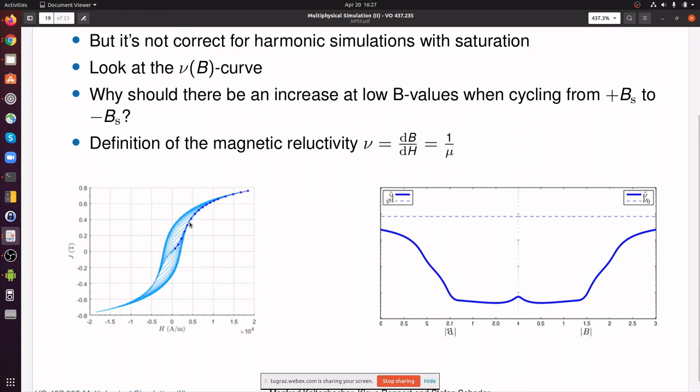So this is actually the wrong material model, and the correct material model would be the so-called anhysteretic curve, or idealized magnetization curve, which is simply thought of as if you narrow the loop until the area becomes a line, then you don't have this Rayleigh region effect here.